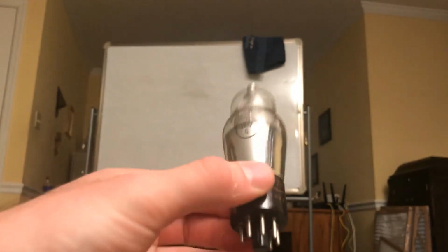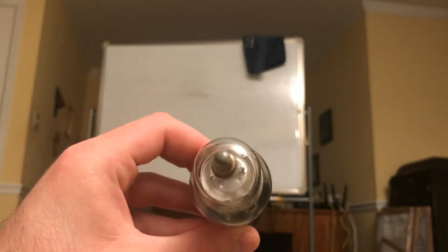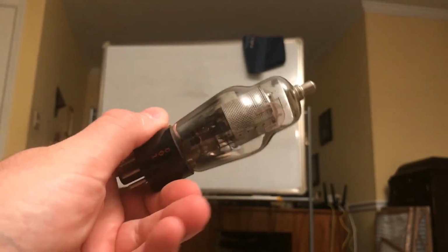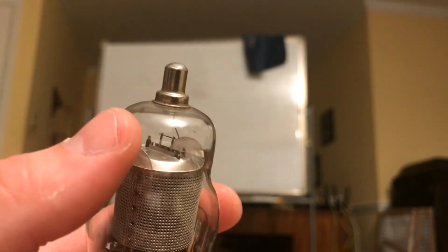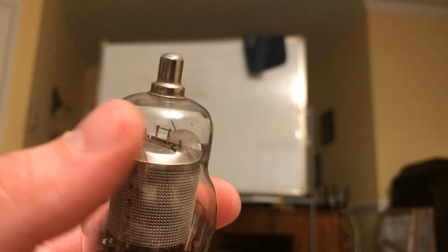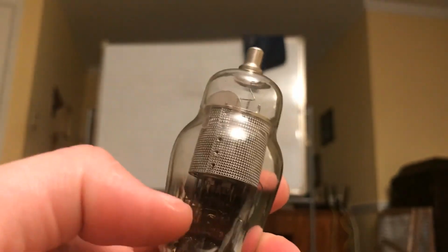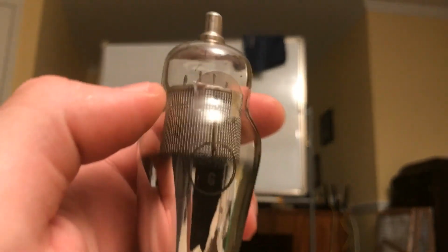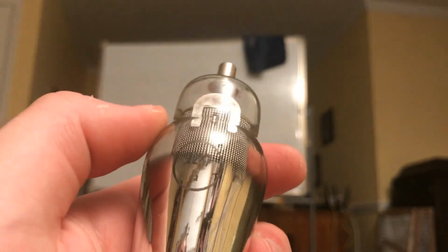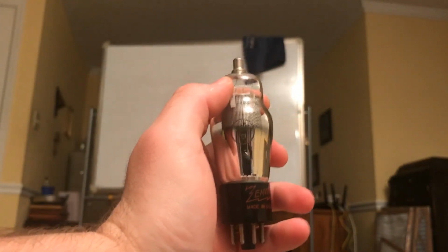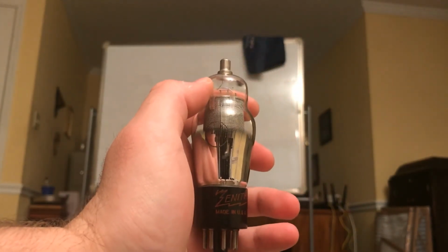An octal base, the top cap that had a wire hooked up to it, the getter, which is this silvery metal that gets rid of the oxides that form during its operation, and then electrodes inside. Here's a close view, although you can't quite see it. The thing that controls this charge is those two in the middle. That's the grid. The filament is in the very center, and the plate's the outer part. Very interesting device. This might actually be a pentode, which is more complicated, but this is a vacuum tube, the first electronic component.